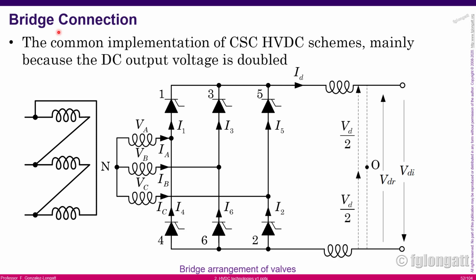What you can see over here, we have a transformer on this side, and on the other side we have also the transformer star connected with some inductance in series, and we have here the three-phase bridge that is used for rectifier and sending the signal, okay? In this case, the device can be working as inverter or rectifier depending on the sequence of elements that are switched on or off.